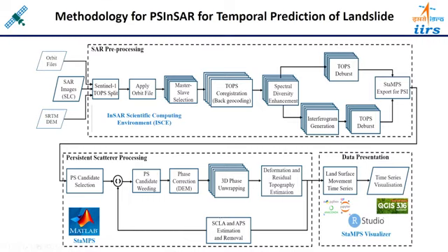So after this, finally the land surface movement time series was observed and visualized using QGIS, Jupyter Notebook, or RStudio software, and the StaMPS PS visualizer also. This particular methodology was applied to Sentinel-1 images, and ascending and descending data sets were used.